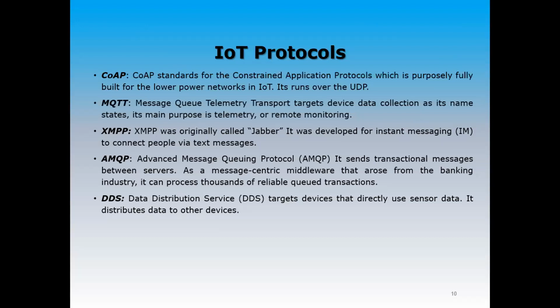There will be many sensors; this protocol is designed for millions of sensors out there generating data, but I will not need the data from everything. So the cloud or the IoT system subscribes to that particular object, and only the ones you subscribe to will have their data published for you. That is the publish subscribe method which MQTT follows.